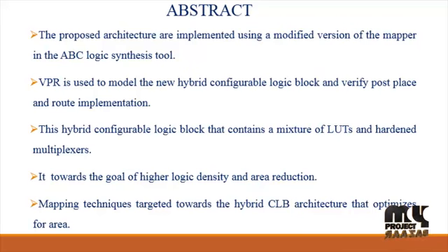These buses share the multiplexer select signal. The second factor, reducing decoding logic, is due to designs containing decoded multiplexers and associated decoding logic. If decoding logic consists of more than one signal, then the multiplexer is best implemented as a decoded multiplexer.